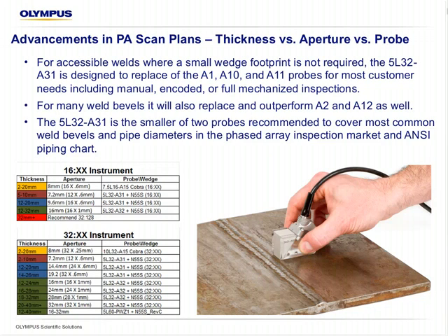So throughout this presentation and in some of the similar downloads for the recent webinars, we're going to see several aperture charts related to the new weld series probes, but also applicable to any probe and wedge in the Olympus catalog. Don't overthink these. These are very simply a chart that defines thickness versus probe aperture, which would be the equivalent of a single channel conventional UT size of the probe.